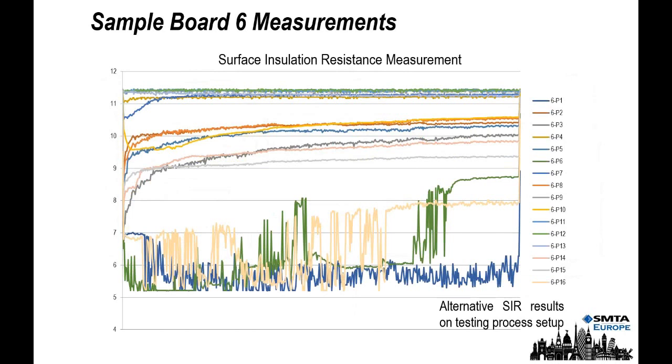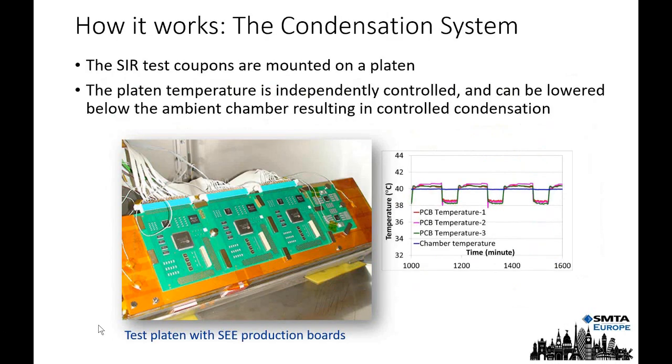So it's actually creating a barrier. Just like in the old days of hand soldering with rosin fluxes, rosin used to protect the surface of the board, and we took it away when we went to no clean, no protection. Having something there does give a level of protection, certainly underneath some of the packages.